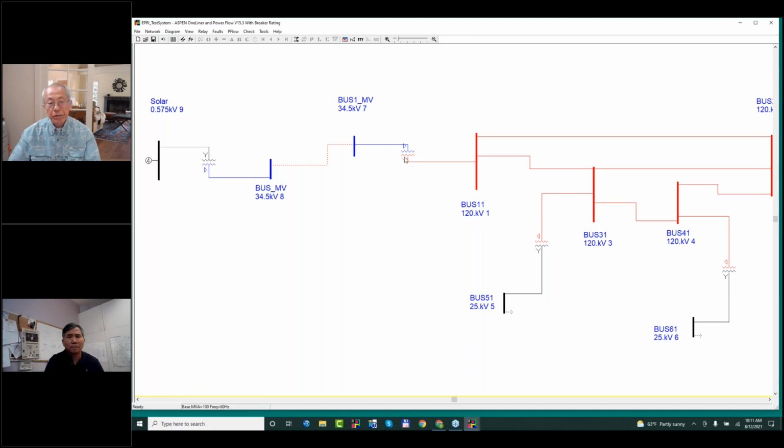And then finally, before attaching to the power system, this goes through a delta-Y transformer in some cases. Then you notice now that you have delta on this side and you have delta on this side. This often presents a problem for single line to ground faults, because if any of those single line to ground faults happen here, the voltage would go sky high. So normally people would either provide a shunt over here, like a zigzag transformer, which is kind of expensive, or they would put a Y-delta transformer here with the Y connected to the 34 kV and the delta not connected, and that provides a shunt.